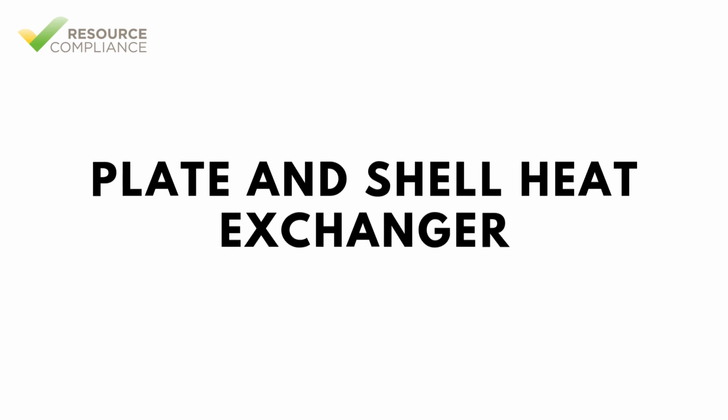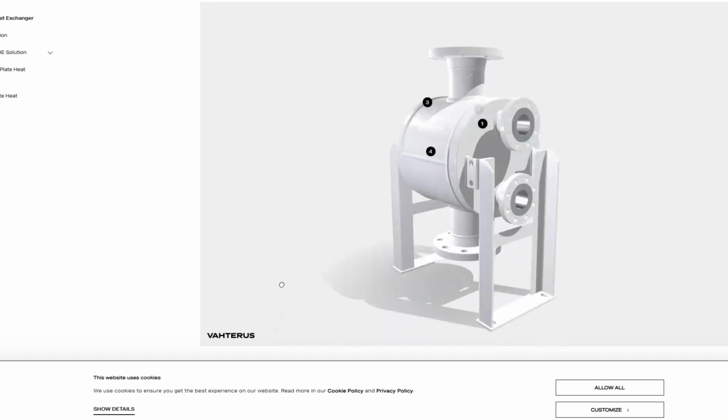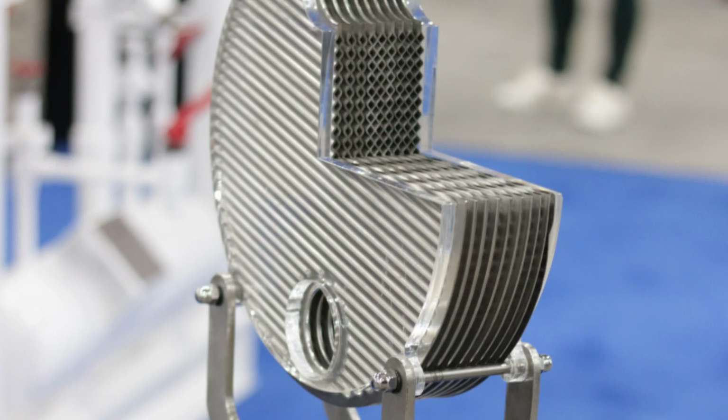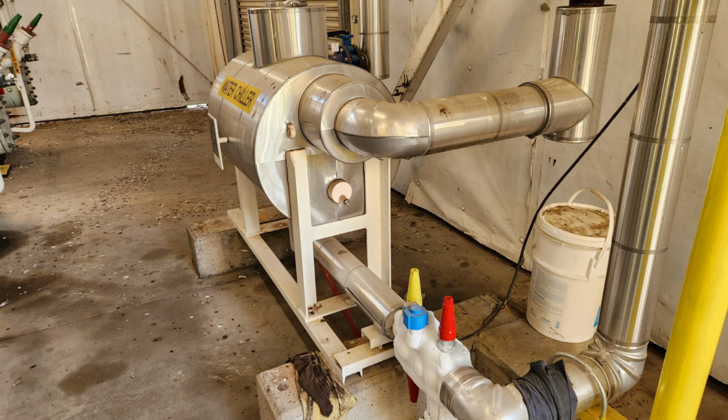A plate and shell heat exchanger is a hybrid design that combines features of both the plate and frame heat exchangers and shell and tube heat exchangers, enhancing thermal efficiency and structural robustness. Plate and shell heat exchangers consist of a cylindrical outer shell similar to the shell and tube heat exchanger, but instead of tube bundles, they incorporate a pack of corrugated metal plates housed within the shell, like a plate and frame heat exchanger. In many refrigeration applications, the shell is fully welded. This reduces the risk of a leak, which is a benefit, but also prevents the heat exchanger from being modified.